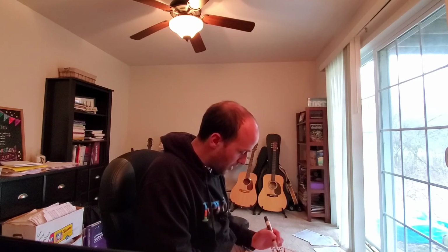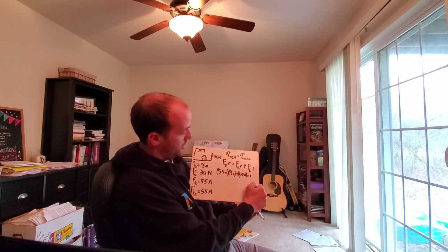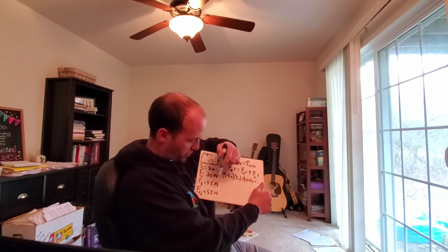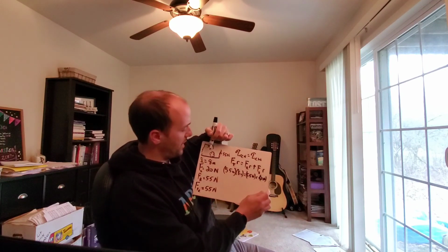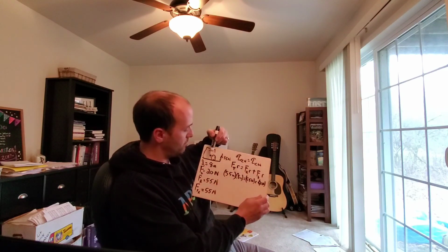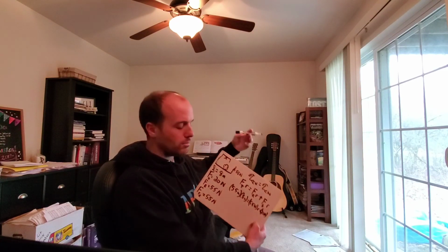So 55 newtons times an unknown moment arm, plus the weight of the beam, 20 newtons. And the moment arm for the beam is at the center of mass. The whole thing is 8, 8 divided by 2 is 4. So that's 4 meters.